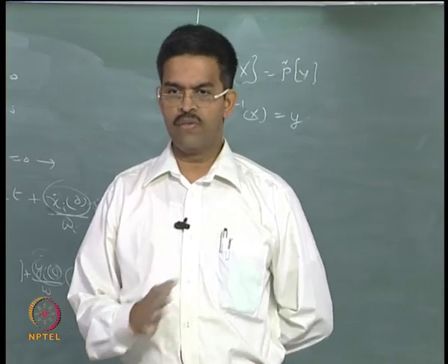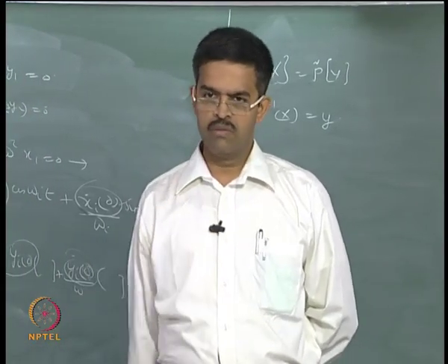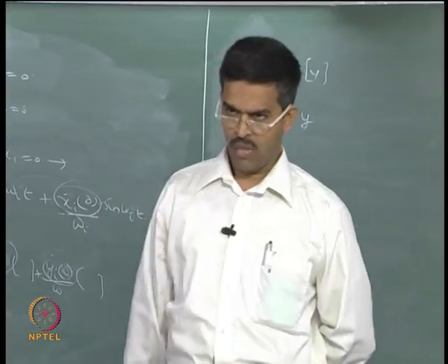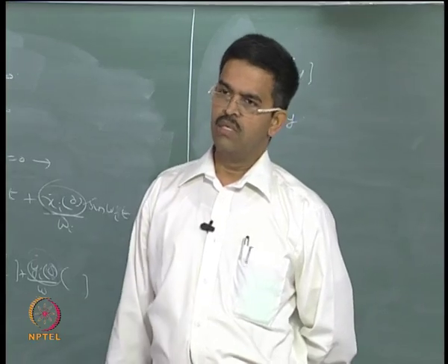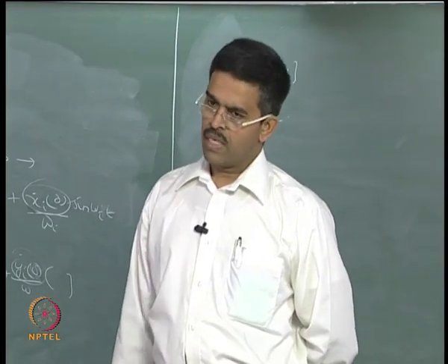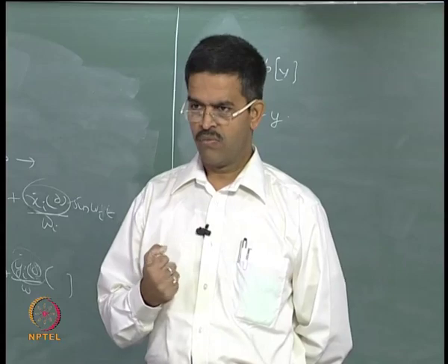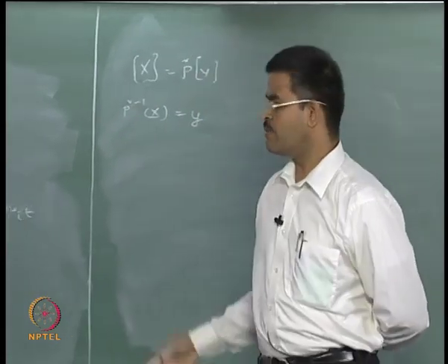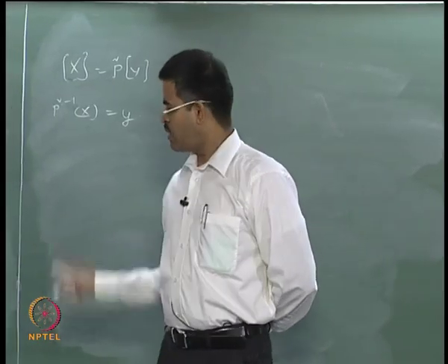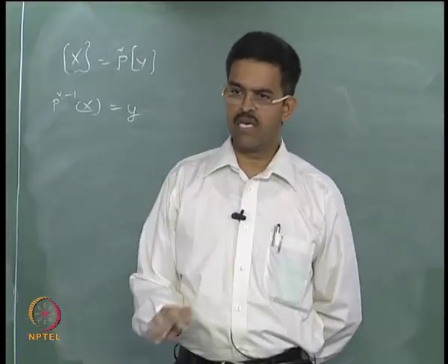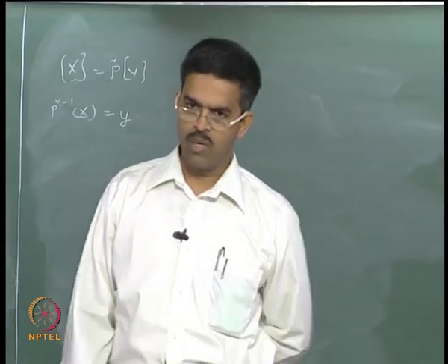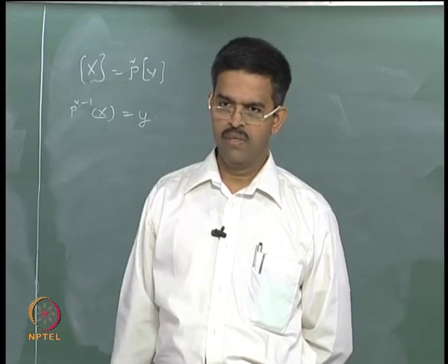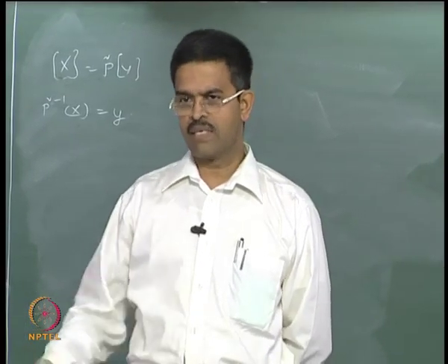What you are going to do is very simple: write the equations of motion, find K matrix, M matrix, solve by any of the methods you already know, eigensolver, Stodola, Rayleigh's, Dunkerley, get the phi's and omegas, you get the phi matrix now. For every degree of freedom find the generalized mass M1, M2, M3 and so on, and divide by that square root value to the phi's, you get the weighted modal matrix now.